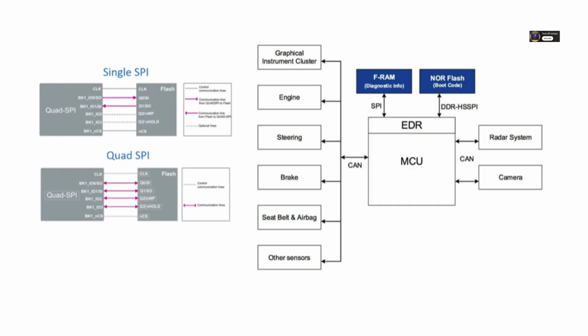To read data, first, pull the chip's CS line LOW. Then send the command byte for a read or fast read. Follow that with the 3-byte address where you want to start reading. If you used fast read, you usually need to send 1 extra dummy byte now just to give the flash time. After that, you just keep clocking the SCLK line, and for every 8 clocks, you read a byte of data coming back from the flash on the MISO line. Read as many bytes as you need. When you're done reading, pull the CS line HIGH to deselect the chip.